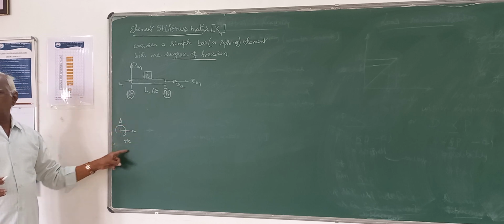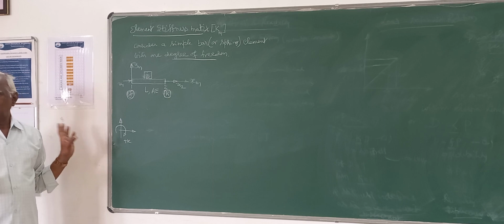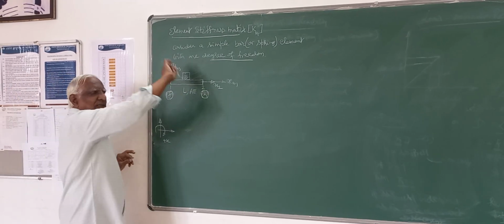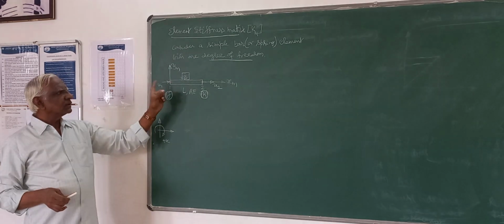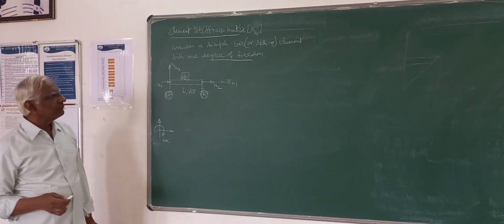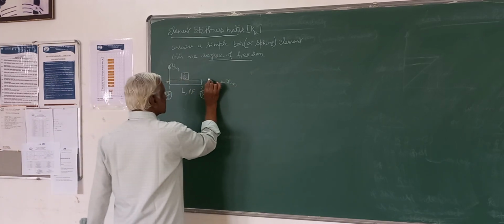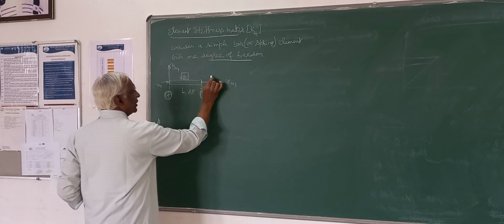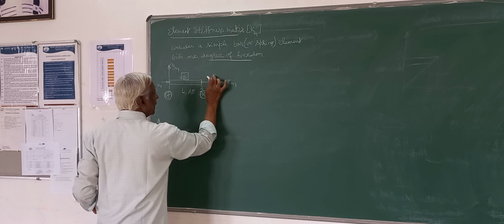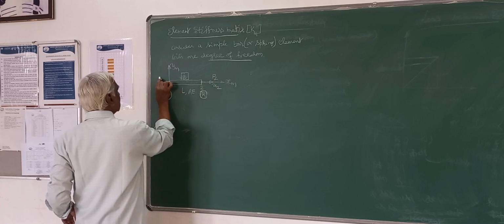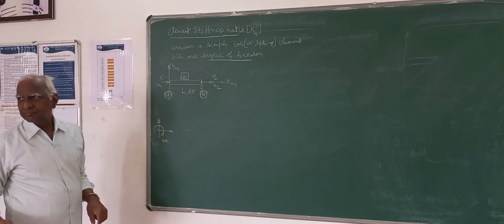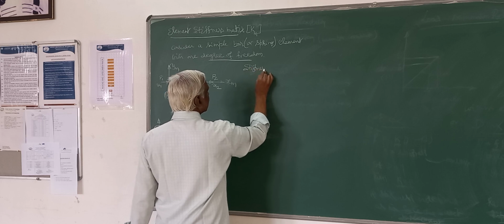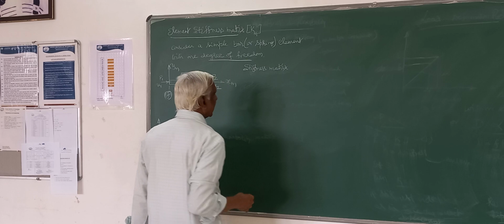Planar structures have only 3 possible degrees of freedom at any end. Here I am considering only 1 degree of freedom. The other 2 will be the vertical displacement and the rotation. So we consider 2 degrees of freedom like this. We always talk about displacements first, then the corresponding forces. Here we call the force P2 and here we call the force P1. So here we always define the stiffness matrix.